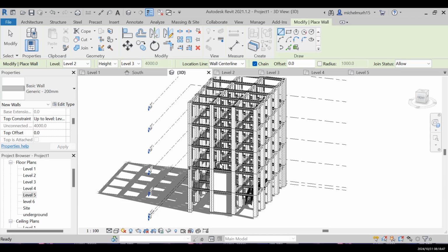If I put the wall on the second floor, you have to start it from the 3rd floor. So it's gonna start from the 3rd floor until the second floor. So it's gonna occupy that space, that free gap that you have designed for it, right? And the wall is also gonna add additional forces on this beam here. So by using Robot Structural Analysis Professional, you have to consider all of these additional forces that you're putting on your beams and your columns. Okay, so I'm gonna talk about that later. So here, first of all, I'm gonna finish my walls.